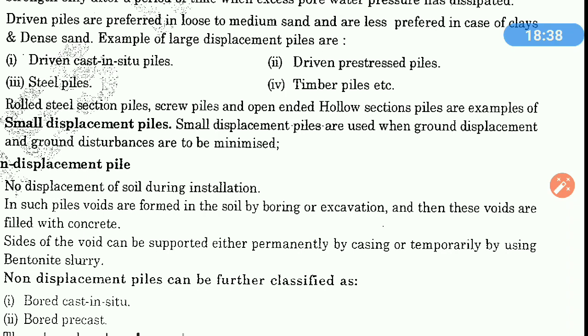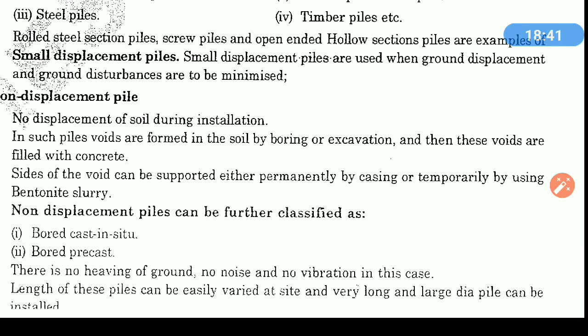Non-displacement piles. Non-displacement piles are those piles during the installation of which there is no displacement in the soil medium. In such piles, voids are formed in soils by boring or excavation, and then these voids are filled with concrete.